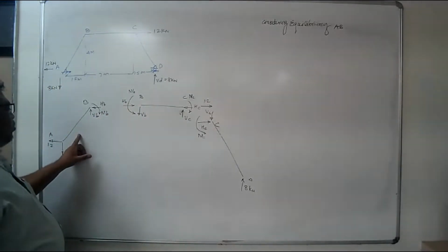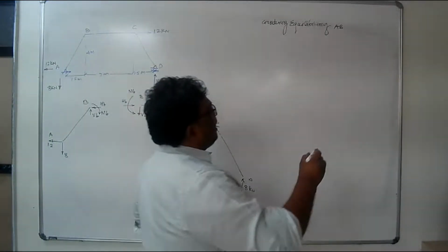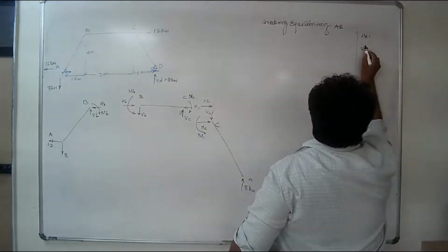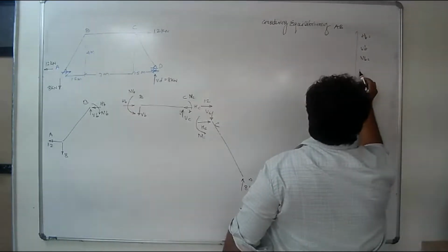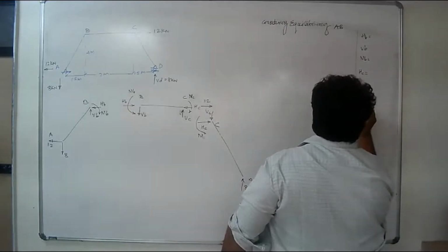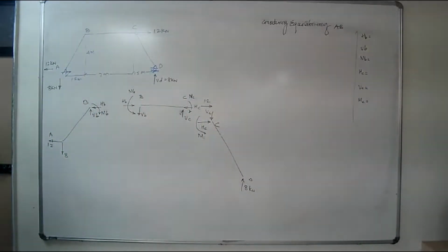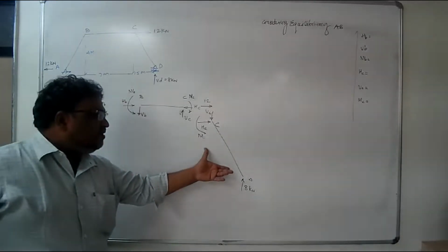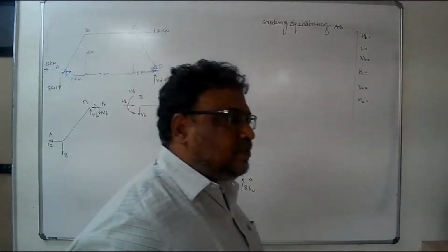तो मैं ये मेंबर सॉल्व करूंगा, उसके बाद either you solve this or this member and you will get the required unknowns. What are the required unknowns if you will see? The required unknowns are HB, VB, MB, HC, VC, MC. These are the unknowns. The rest of all are known. There are 6 unknowns. इसके इक्विलिब्रियम के लिए 3 इक्वेशन है, इसके इक्विलिब्रियम के लिए 3 इक्वेशन है, इसके इक्विलिब्रियम के लिए 3 इक्वेशन है. So if you will see, in all there are 9 conditions available.